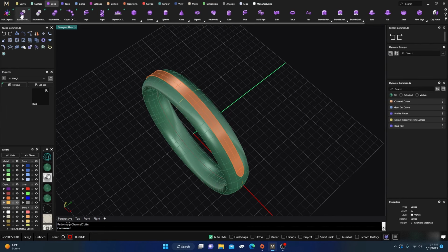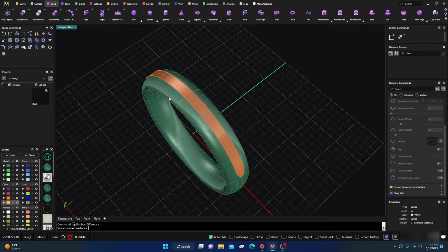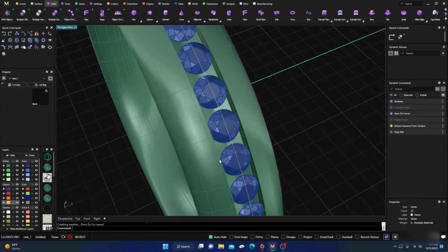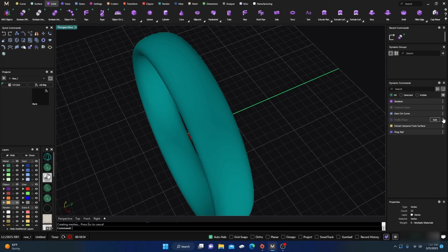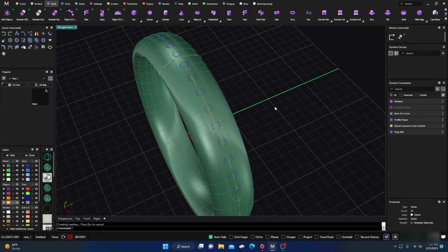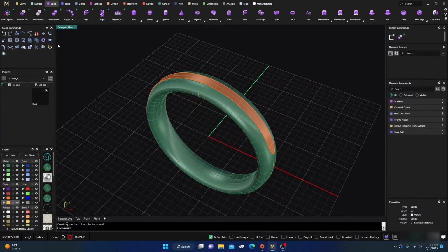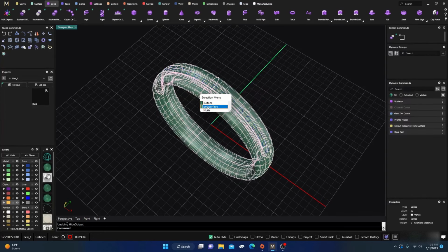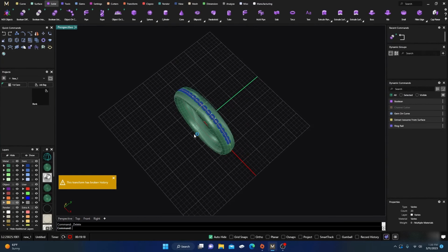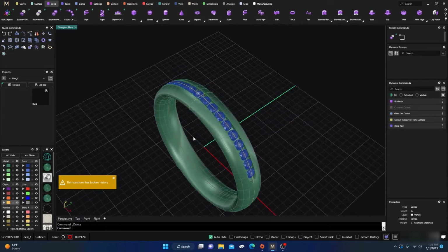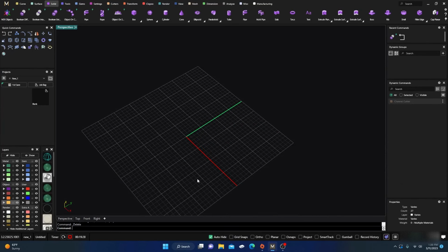Okay. So let's do that same thing. We're going to go to Boolean difference. We're going to cut this surface with this surface and hit enter. Right away, it hides my cutter, right? Basically, it's just hidden over here. So if I go here, I can show it. Well, usually show it. Show. But it's not. Okay. Yeah, there we go. Okay. But it'll automatically hide it for you. So you don't have to go back and do all that extra work of hiding it or getting rid of it. It just automatically hides it. So that's a good option to have on occasion.